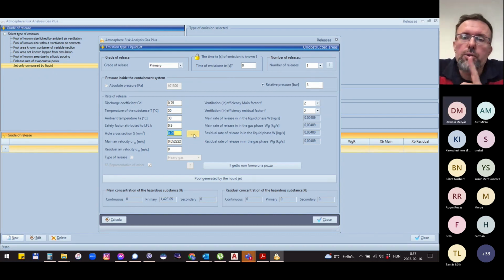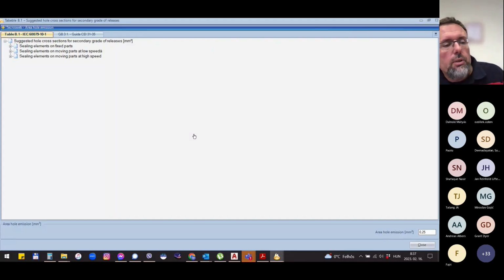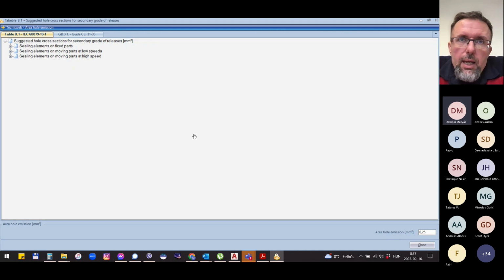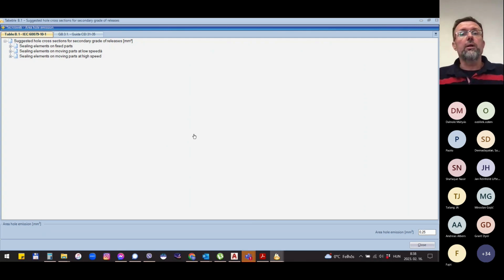The whole procedure. So sorry, Mátyás. One point. Even the IEC 60079-10 says that you have to consider the aging. Yes, okay. The aging of the seals, the aging of the gaskets, the aging of the technology. Especially in environments with high ambient temperature, like in the Middle East. Aging is a very obvious topic. Okay, so here you need to consider this topic very seriously while you are doing the design, while you are doing the hazard specification. Yeah, absolutely. You're absolutely right.